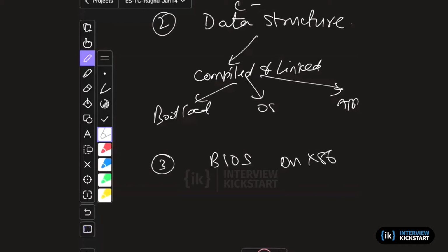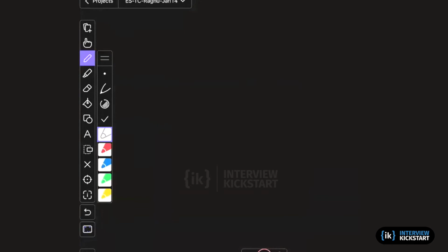So the BIOS takes away the dependency, but it is C code, and you have to build the BIOS for that platform, which is reasonable in the PC world. The OS is shielded from this data, but changing any hardware is not possible. The better way, so, is basically device tree.